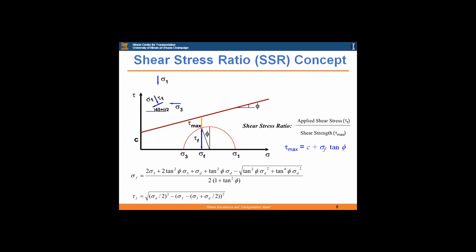In the fundamental theoretical plasticity theory for rate-dependent and rate-independent materials, you need stresses to decide whether you're going to fail or not, plus which direction you're going to fail, the dilation or normal dilation of shear-type plastic deformations. And the amount of plastic deformation is governed by the incremental changes in the strain. So in one version of the model, we were heavily going on the strain. In this version, we are going on the stress.